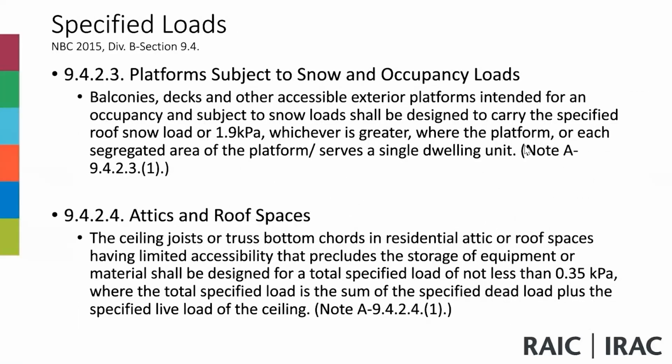Down. Specified loads, these are some provisions in 9.4. In 9.4.2.3, platforms subject to snow and occupancy loads: balconies, decks, and other accessible exterior platforms intended for an occupancy and subject to snow loads shall be designed to carry the specified roof snow loads or 1.9 kPa, whichever is greater, where the platform or each segregated area of the platform serves a single dwelling.